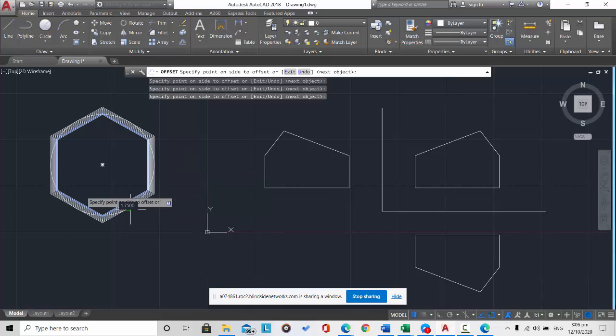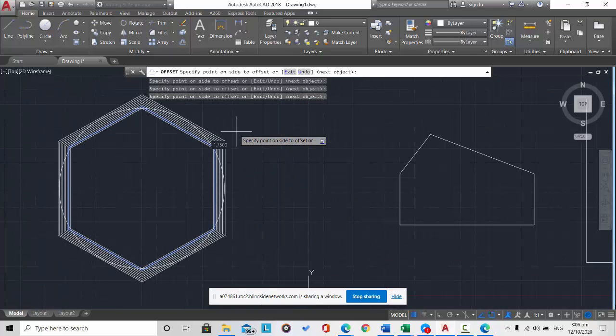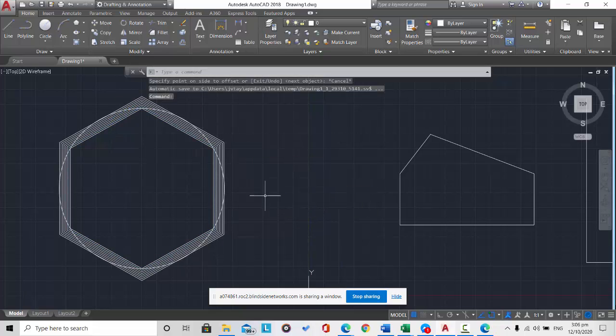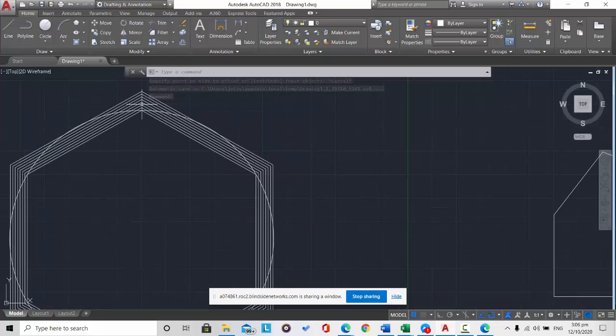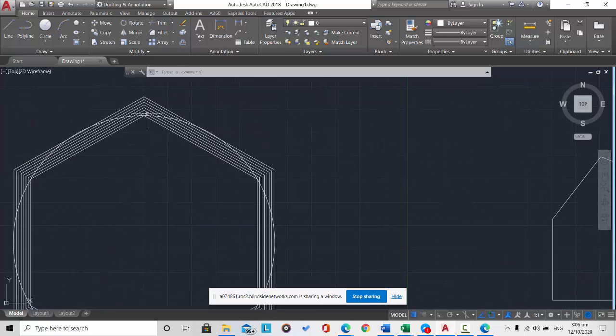and let's say we have this drawing now, okay, and we need to trim those lines, where the circle will be our cutting edge. So we need to select the circle as our cutting edge or boundary. So how do we do that? Of course, we cannot just choose the circle, right? We need to zoom in to be able to choose the circle. Okay? But make sure you are selecting the circle as your cutting edge, no?